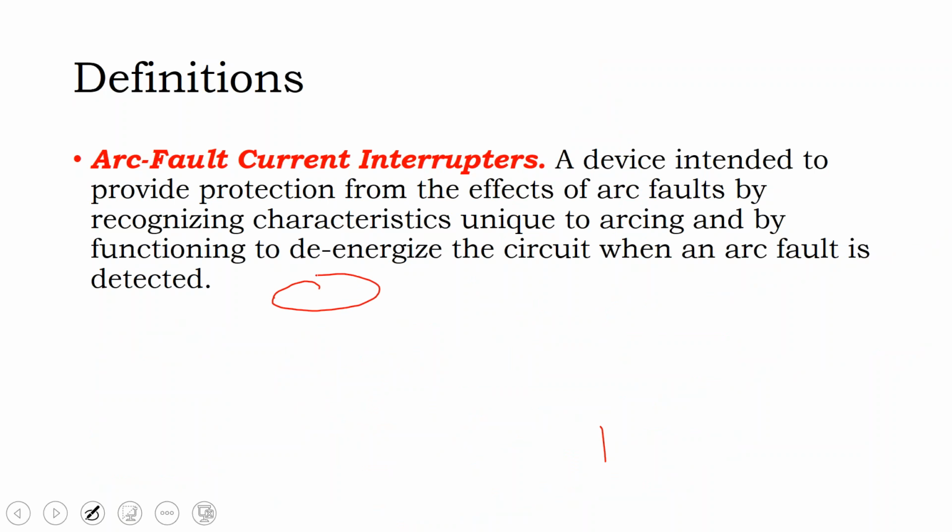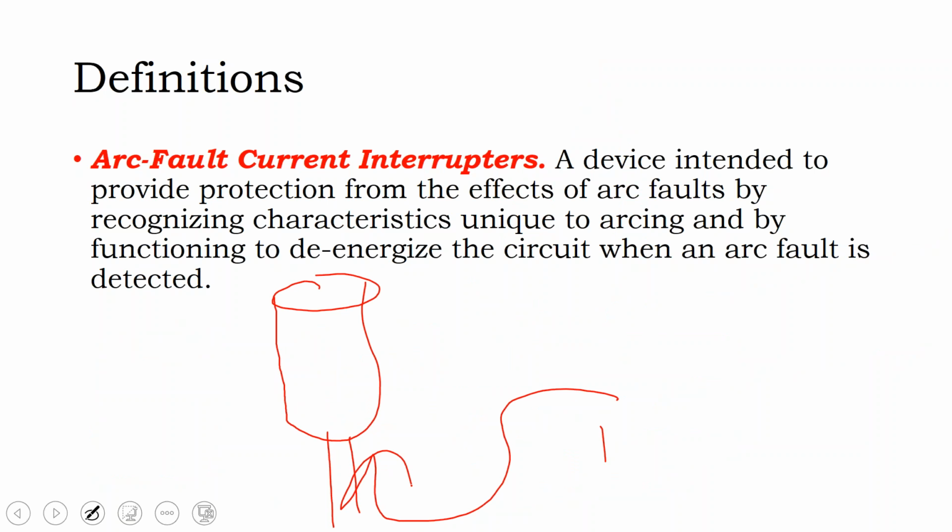So here's our housing for our solar cable. This is from the solar array going into this housing. Inside this housing, there's a crimp. The crimp sheathing goes around the conductor, and you strip out the jacket. There's a thicker cable jacket, and you strip it out so that just the copper is exposed.